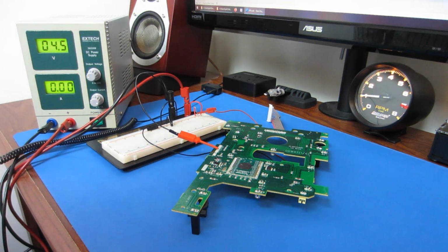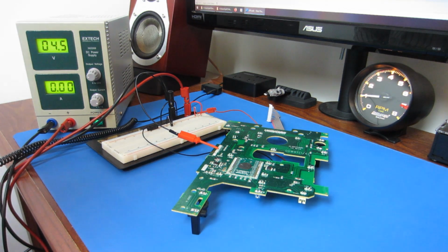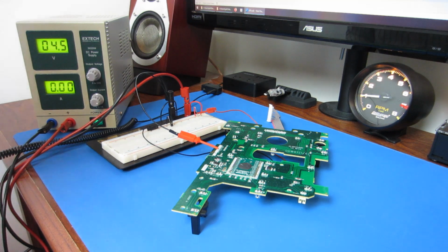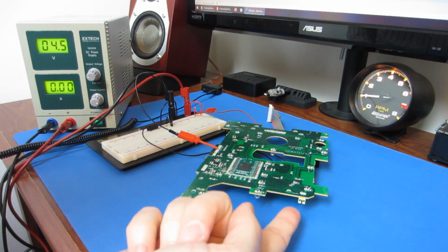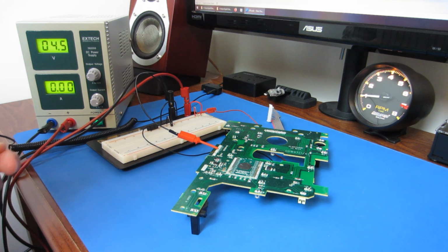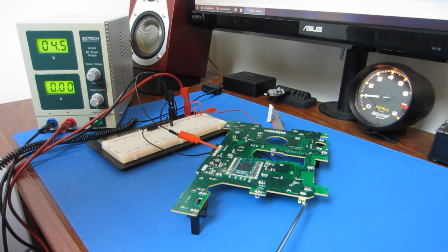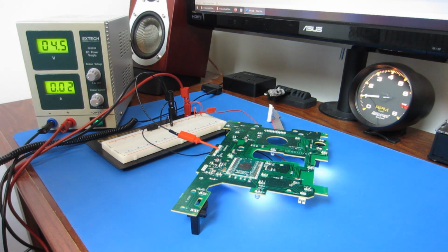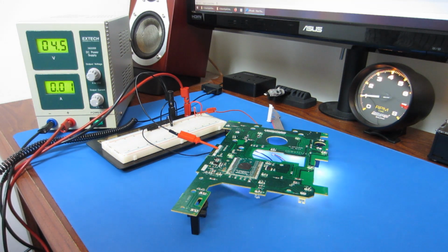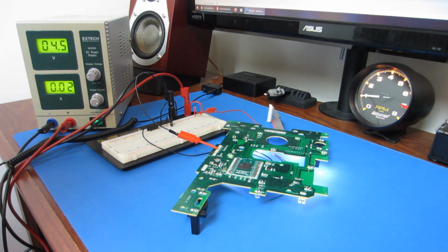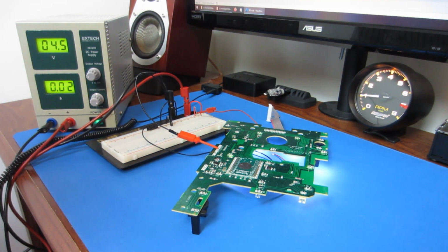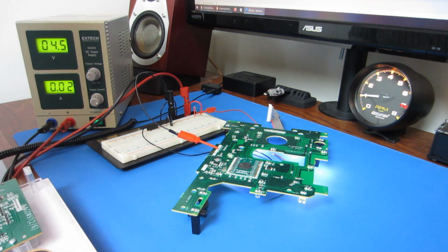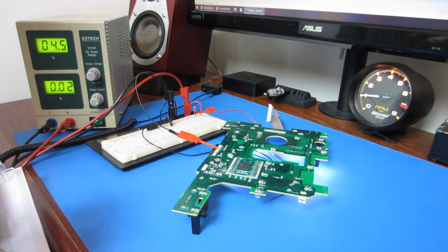But if you remember, it didn't actually do anything until we activated the start button. So the start button plugs in right there. If I disconnect those two pins with a metal screwdriver. Oh, there we go. Now the board is powered up. So at this point we should be able to hook the Backbox back up to the playfield and see that SPI bus in action. I'm going to pull power first.